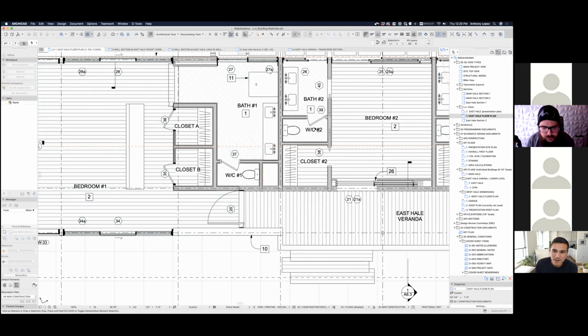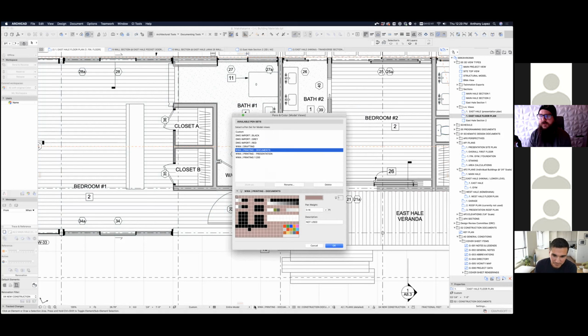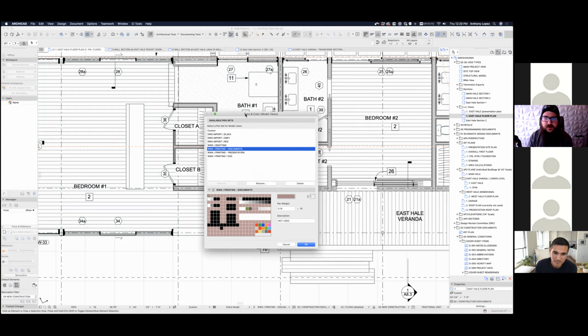Did you implement the pen setup? Anthony sort of developed this in parallel to the template updates. So in the template, there are actually these two pens right here, which are meant for the white skin separator and white background foreground fills for those new building materials, so that we can look at them with this full detail at say 1/2 inch or larger. But then in our actual 1/4 inch, 1/8 inch documents, those are all going to go to white. Correct.